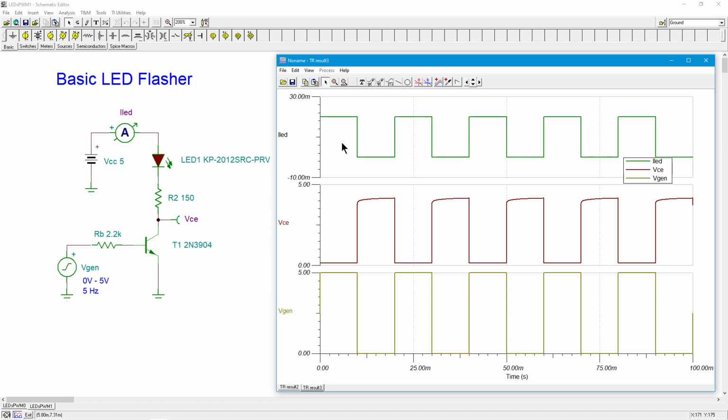It's kind of like you grabbing the wheel as it's spinning and giving it a little bit of a nudge. If you give it a big nudge, your hand is on it for a while, you're going to get that thing to go pretty fast. If you're just giving it a little tap every now and then, that's like a small duty cycle. It's not going to revolve quite as fast. All right. So that's essentially what's happening there. There's inertia involved, and it really is smoothing this thing out.